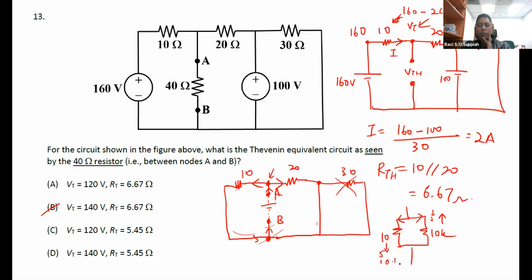All right, and you will see that effectively there will come a time where all the current flows through this because it becomes almost a short circuit. And no current will flow through the 10K ohm. So the same thinking applies here. When I have 2 pathways, one path here and one path here, the current will always take the path of least resistance. So the least resistance of all is always a short circuit.